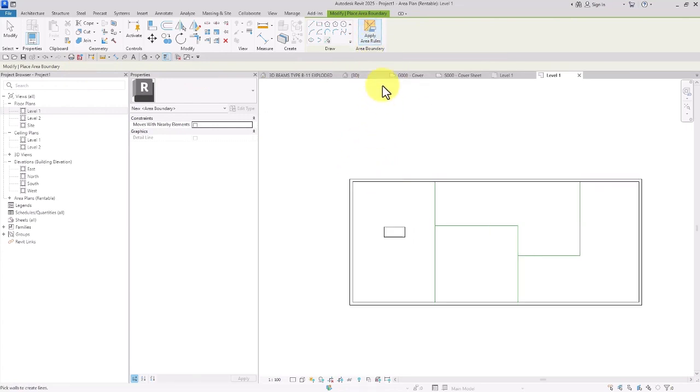If we leave this activated and try to create or draw the boundaries of our area, we would need some specific elements related to the boundary itself. For example, walls. See, lines or other elements cannot be selected here. Only elements related to walls can be selected here. However, if we deactivate this option, we would be able to work with any elements that we want, because we are not working on a specific boundary anymore. And again, now we can find this option in the Ribbon instead of the Option Bar, so it is more accessible.